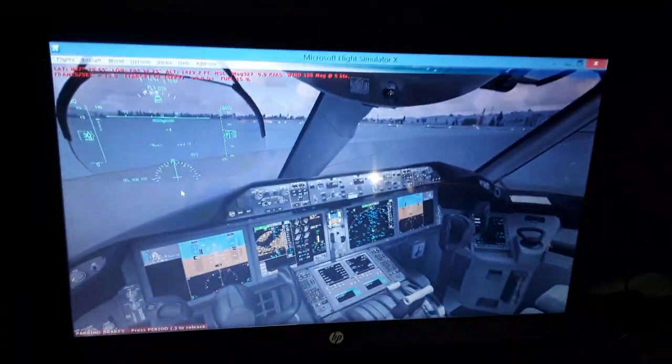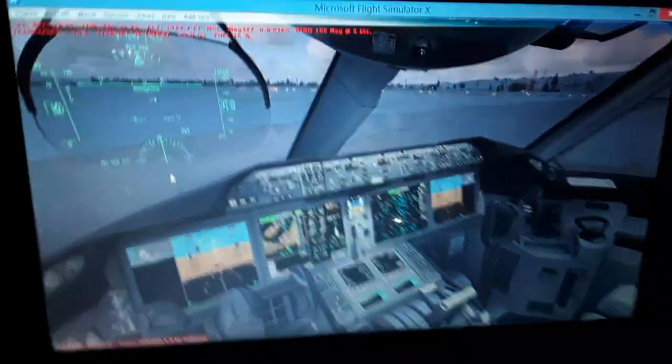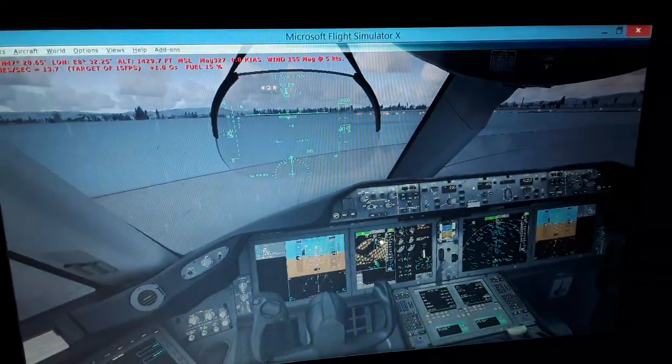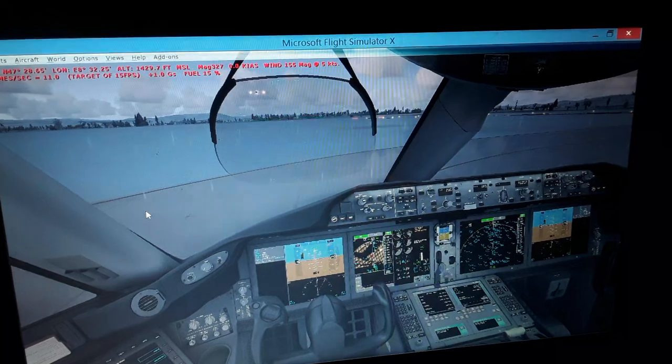We're going to have flaps 25 to 30 degrees for approach and landing at airspeeds of 150, 160, 170 knots. Also we're going to have a pitch attitude of 9 degrees and the landing gear extended. You're going to see the complete flight from takeoff, climb, cruise, descent, approach and landing in the end part of the video, so stay with me until the end. You can see the complete flight over here.